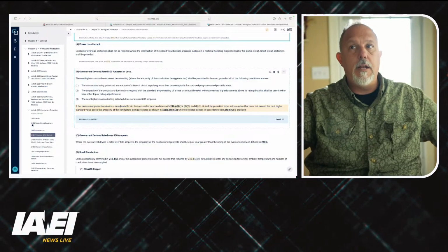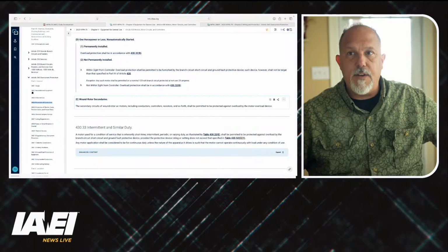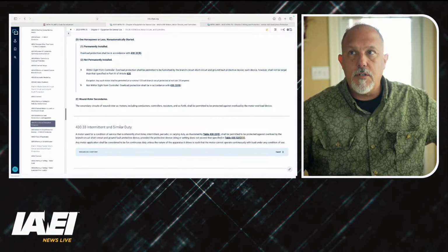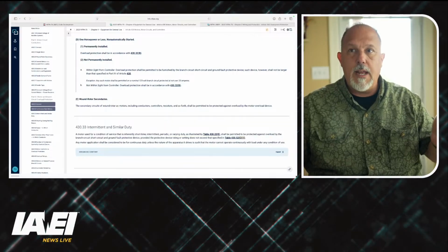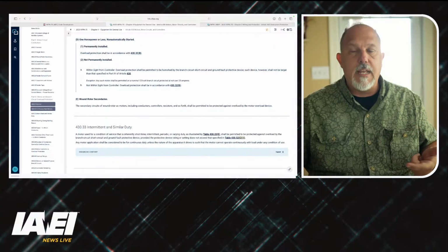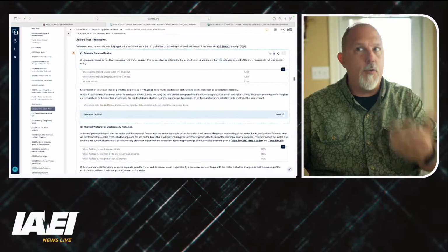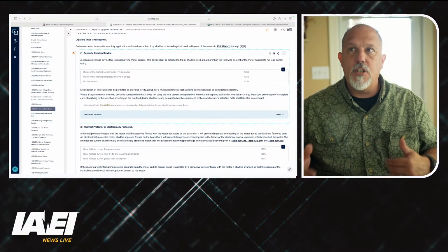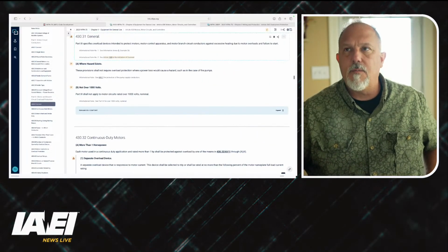But there's nothing in 430 that I could find that I'm thinking in part, and I agree with what Laurel said. Laurel is pointing out the fact that in 430.31, it has a general statement, but my problem is that all of these requirements say motor protection. It doesn't say motor and conductor protection. It just says motor protection. Now, let's go back to the general. Maybe I'm reading something wrong.